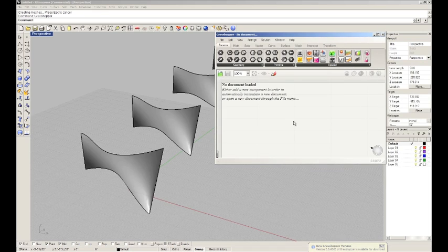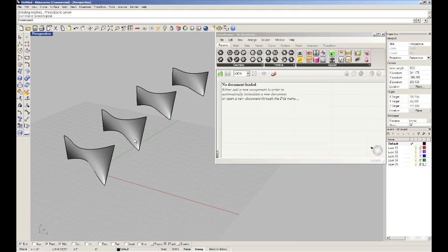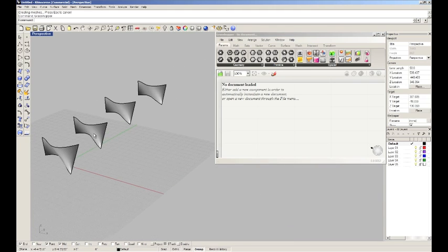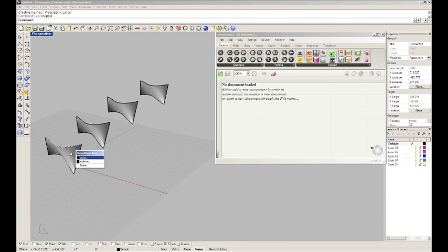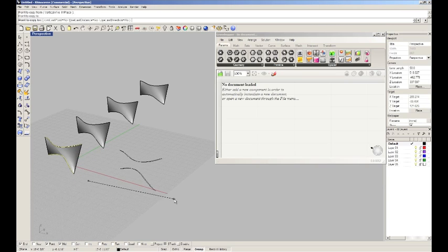As I said, it grew out of the implicit history in Rhino, where the code was hidden and you didn't have any control over it. It developed into this explicit version of history where you do have control over the relationships and how things are working. So I'll demonstrate this again. I'm going to make a copy with no recorded history on of these two original curves that we started with. So copy and move them over.